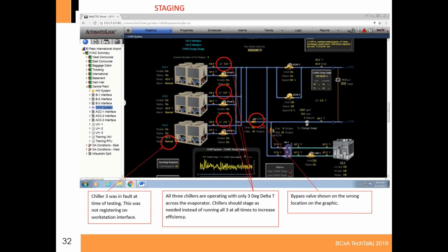The problem that you have to be careful of is, you have to have a third thing to reference so that the controls contractor can pass or fail your test. It can't be just up to whatever he wants. It has to be the design and then the submittal, and then his actual installation has to match the submittal. So that's how I would verify the graphics.